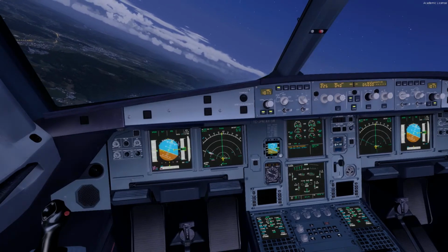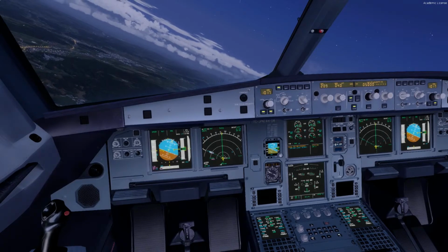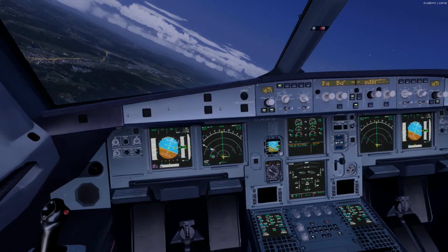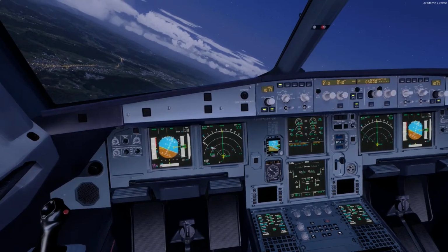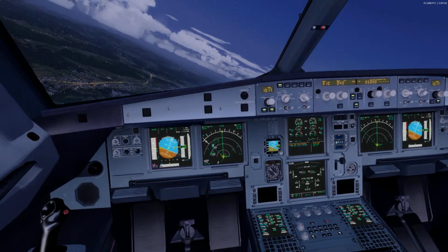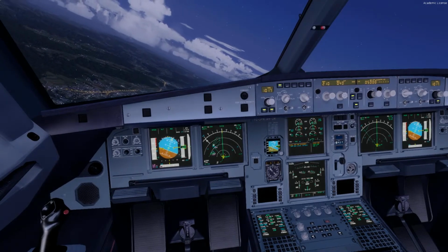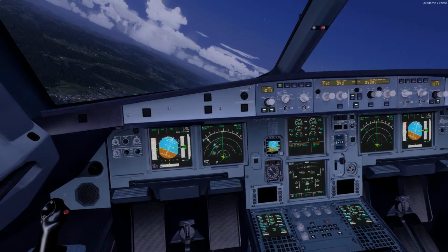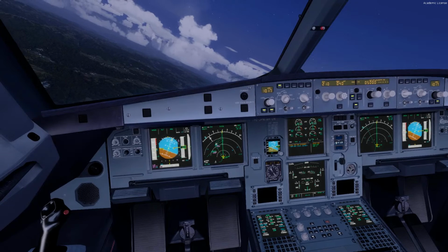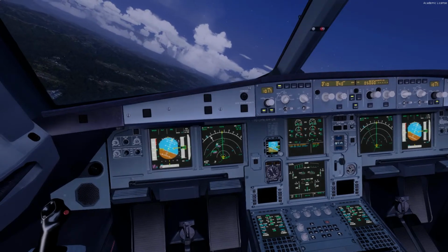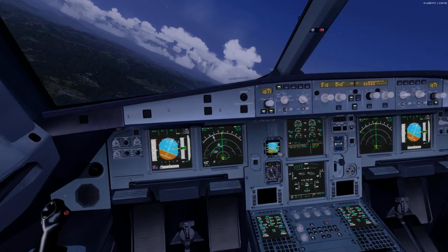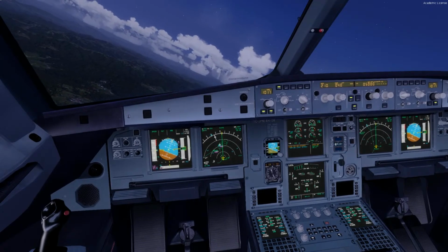Turning to base now, we'll set the speed to 10 and we'll set the flaps number 1. We'll need to take it a bit slower in now, as we're a bit faster on the previous approach. Sierra Golf Yankee, we're going to be slowing down for the IFR traffic. Sierra Golf Yankee, roger, thank you.